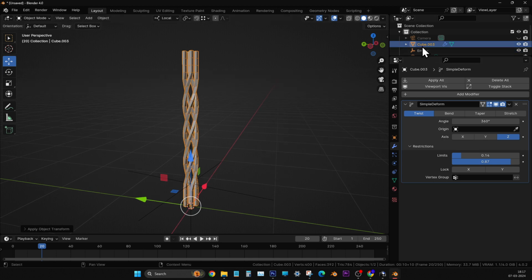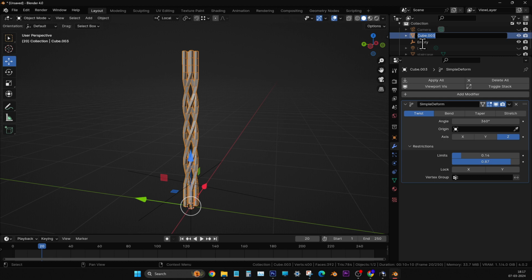Right. Now, very interesting. This simple deform is also there in Maya software; they call it non-linear deformation. Here in Blender they are calling it simple deform. It's very interesting. Many nice animations and shapes we can do with this. We need not do this twisting manually.